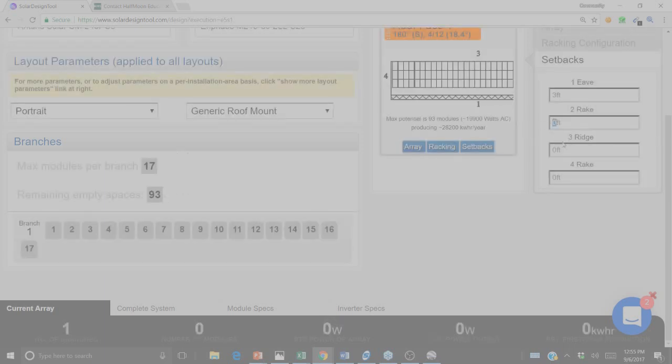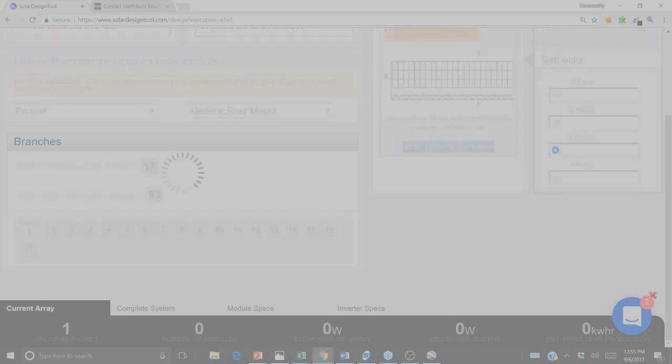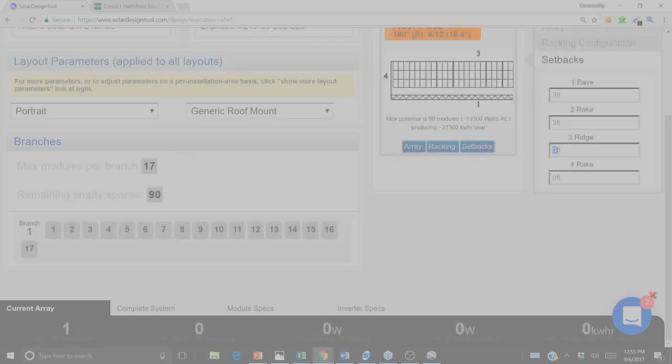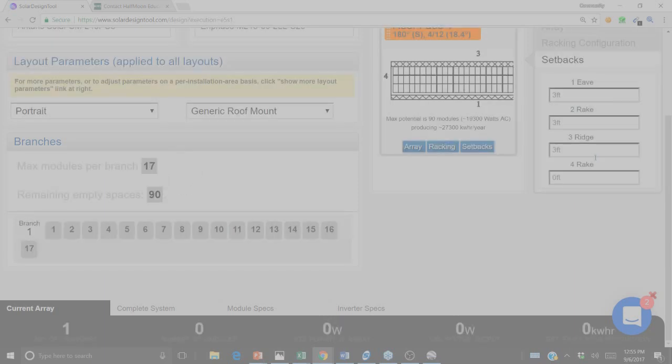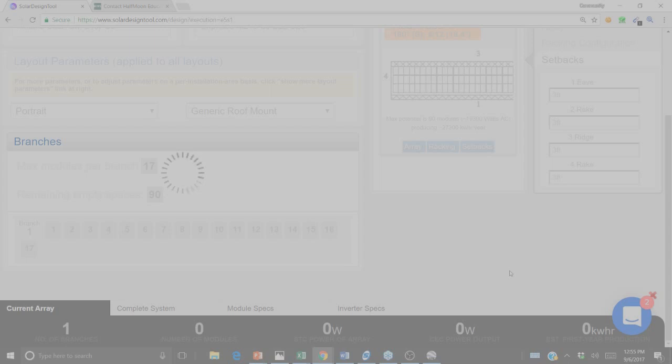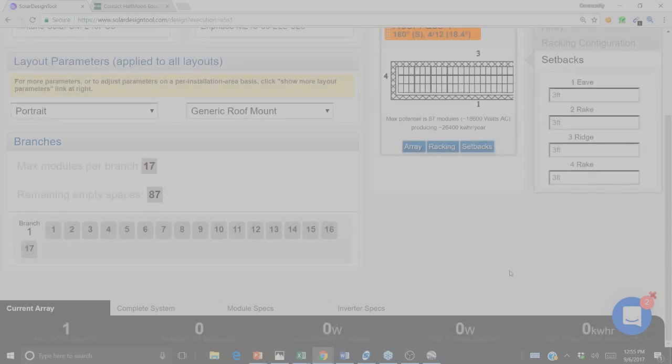And since we're talking about code class, there are other parts of code beyond National Electric Code. For those who are here for the NABCEP continuing education, you're well familiar with the 3-foot offset rules, 3 feet off the sides of the roof, 3 feet off the top of the roof. That's when there is no forced air ventilation system to ventilate smoke during a fire out of the attic.